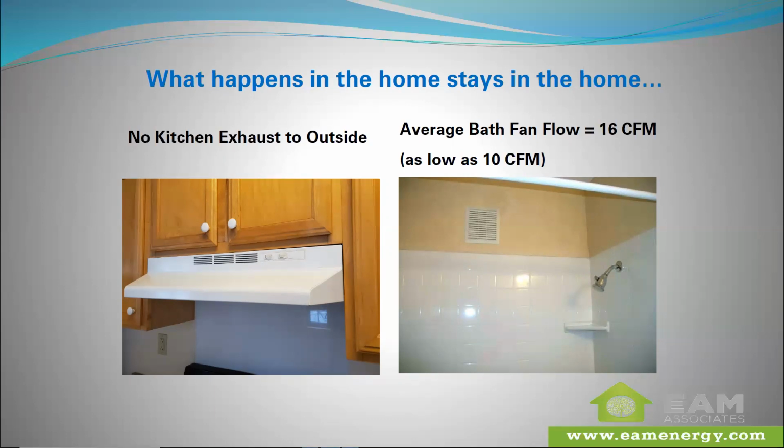So at 50 CFM of air, the amount of air that you're going to move during that 20 minutes, a fan that's only moving 10 CFM would have to run for hours and hours to move that same amount of air, and that's just really not going to happen. The other thing is that a good operating bath fan running during a shower event clears the air a lot more effectively while the vapor is in the air.